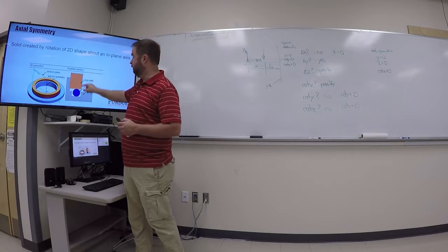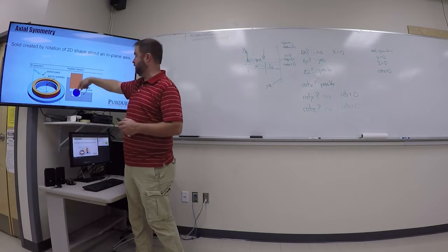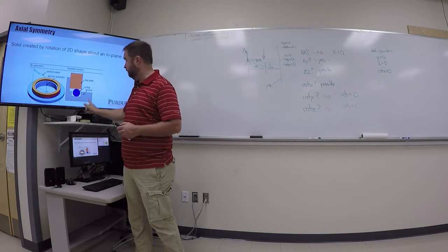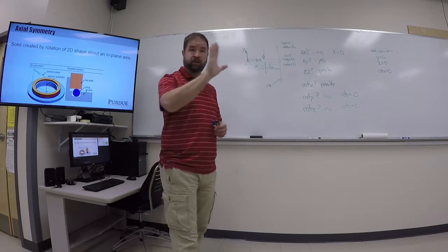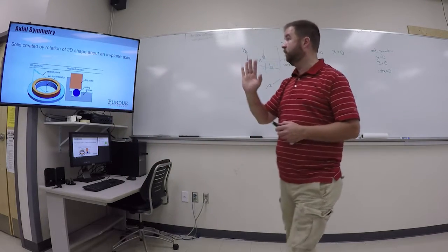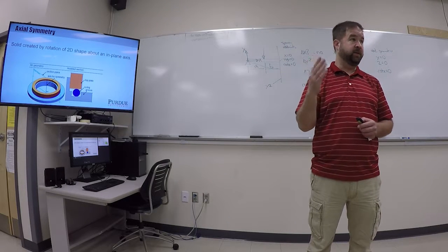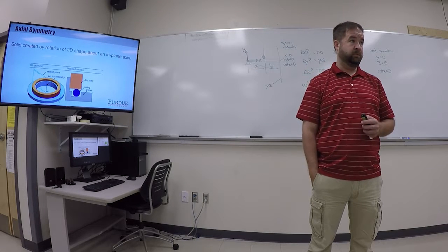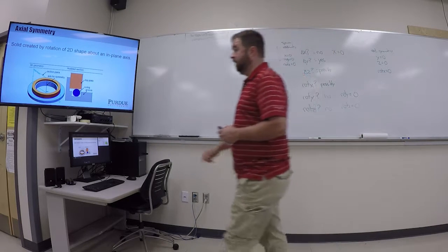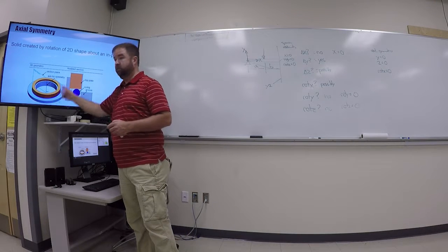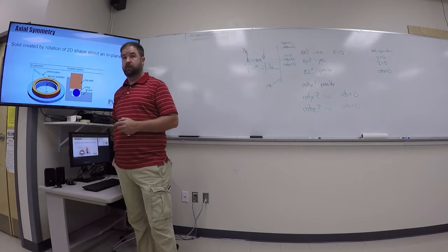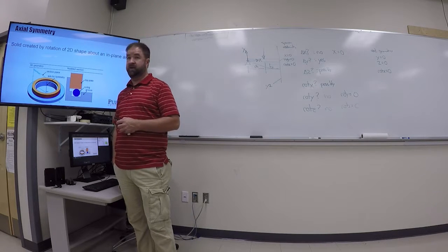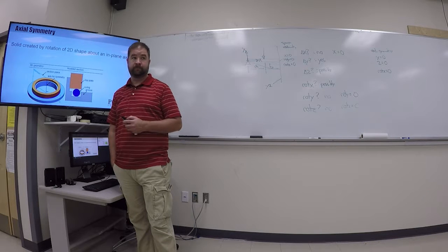Okay? So I can model the rectangle for this piece that's compressing the O-ring. I can model the O-ring as simply just a circle, and then the geometry of the groove, planar, and all I have to do is tell the software that this is the axis of revolution. Okay? And then I just model this, and then it will take it and apply the results around the whole thing to show you what it looks like in 3 dimensions. But it greatly simplifies the math, which means you get a result much quicker.